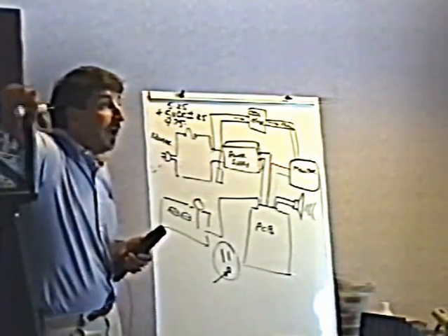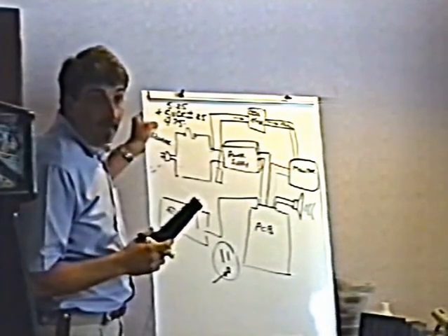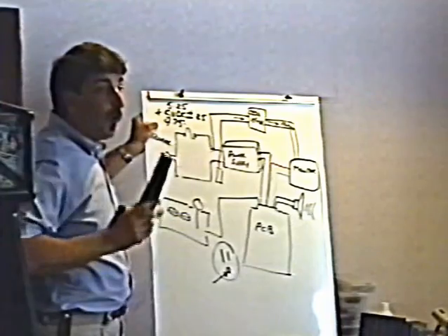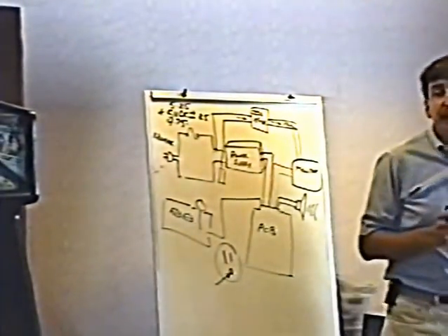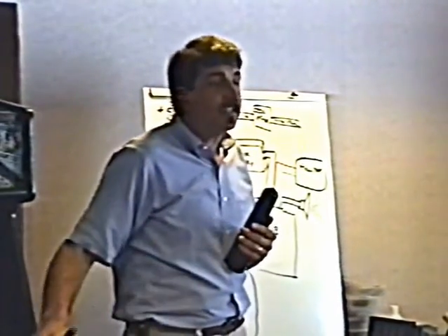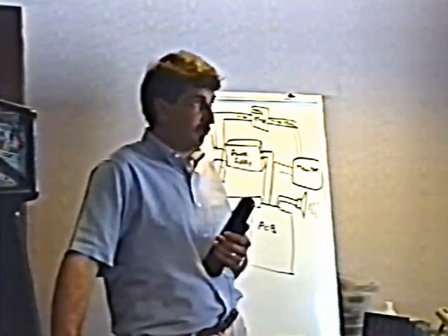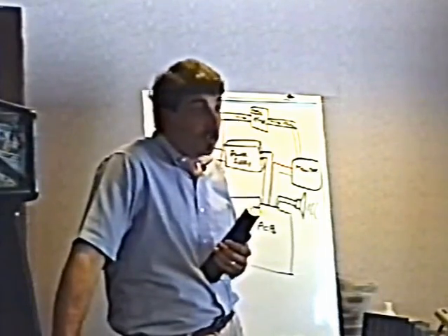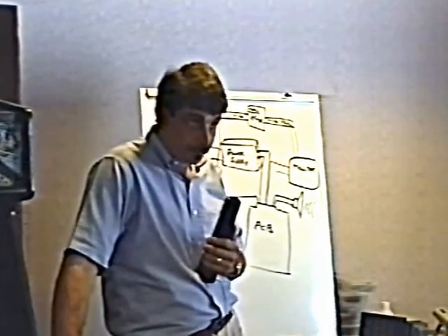Quite frankly, I find that almost nothing works properly at 4.75. Especially like Sky Shark here, it'll crap out at 5 volts even. At Area Amusements, we set all of our games to 5.1 volts. We set the power supplies to 5.1, some people say 5.17, well, whatever, 5.1, 5.15, something like that. We just have found that we have far fewer problems that way.